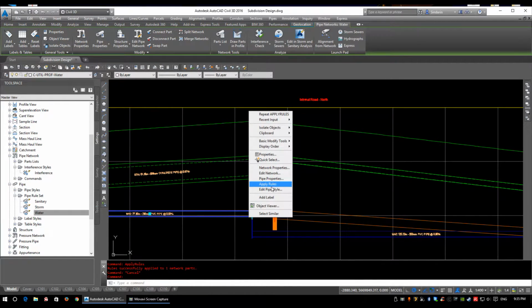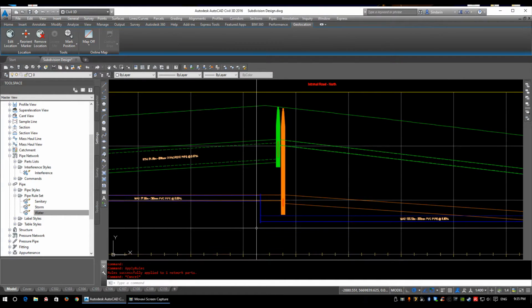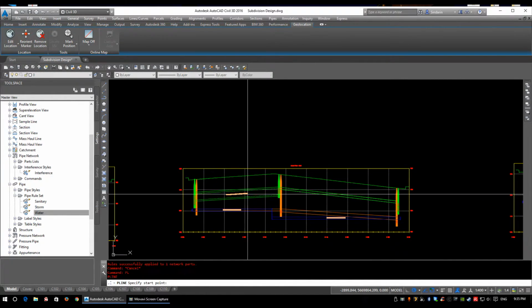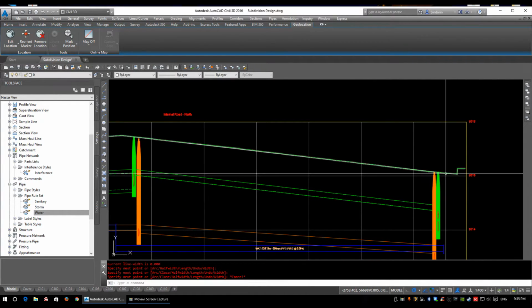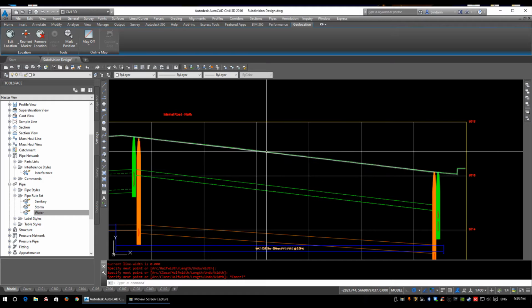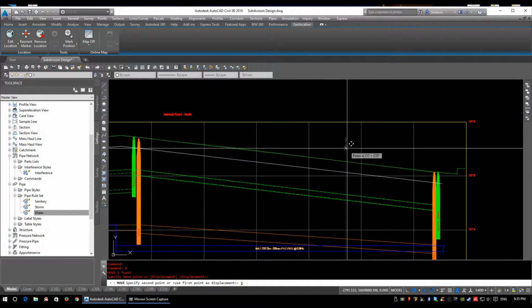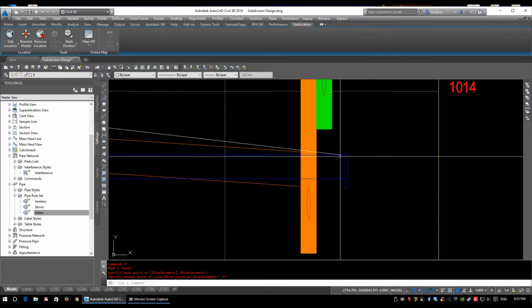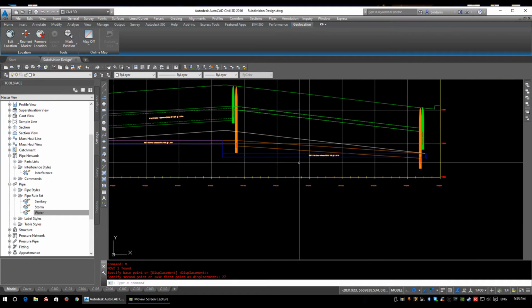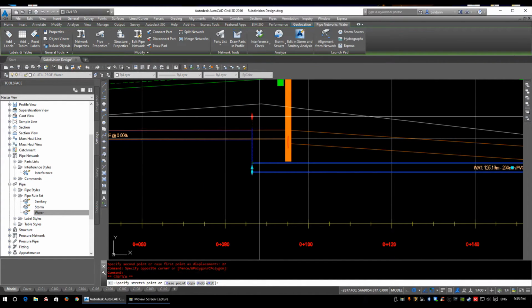And as you see, this is not a perfect process. So things may have to be adjusted manually. And again, the best way of ensuring that everything is proper, I'm just going to again draw a polyline, and I'm going to drop it 27 this time, so that's 2.7 meters down. So it's looking like it's holding the 2.7 on one side, and it's applying a 0 slope, so that's why we're seeing a flat pipe.